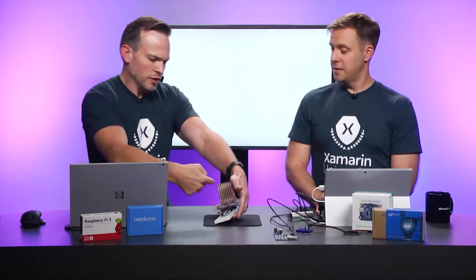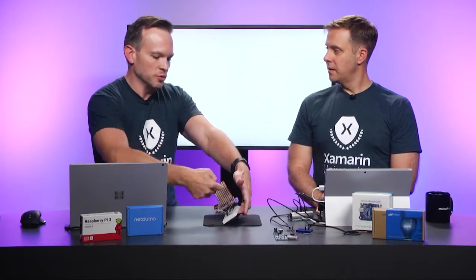So you're doing a bit of heavy lifting here on the device. Right. What we end up getting is, if I want to know the position in space of this device, I get gravity in 3 dimensions. I can get gravity this way, gravity this way, and gravity that way. So X, Y, and Z axes. Well, really how it's affecting each axis based on the orientation of the device. Exactly. If I twist this a little bit, then I have a little bit of gravity affecting my X and a little bit of gravity affecting my Z. Right, relative to the device. Exactly. The Y-axis is still going this way, so it doesn't really care that I twisted it.